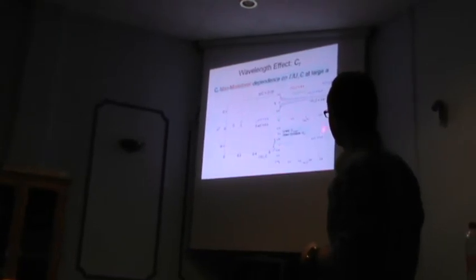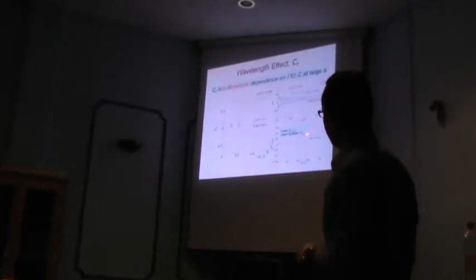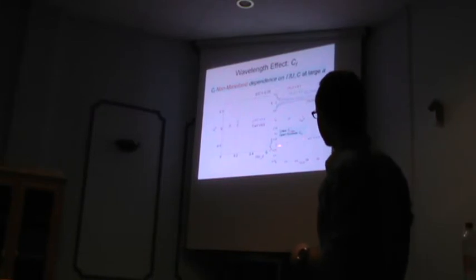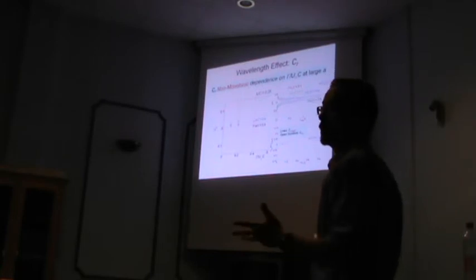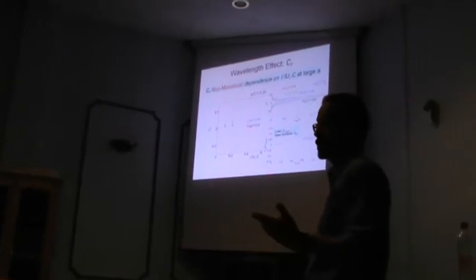And in fact, if you compute the CF mean versus gamma from just the CF mean by itself over here, and just the CFP, the pressure drag coefficient, from over there, you can see how initially this is rising at a faster rate and overcomes the CFP, but eventually this one actually takes over. So this up here is bigger than this over there, and the net effect is opposite to what you expect.